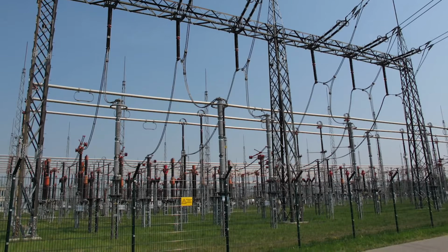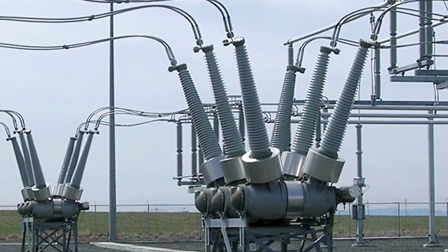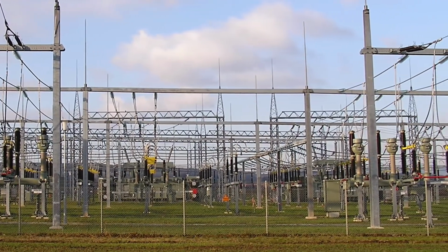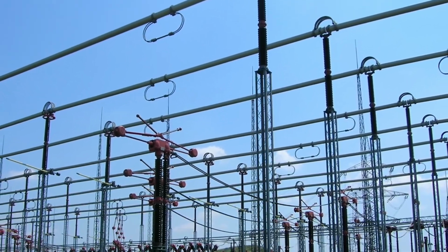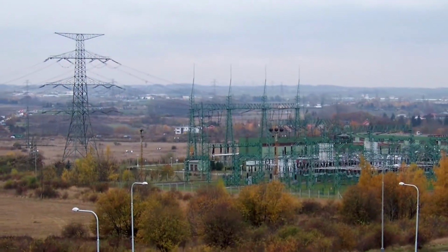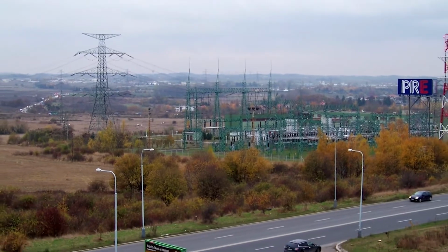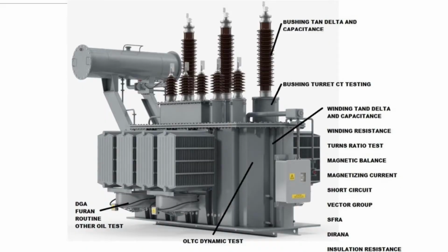Cover the transformer testing. A few of the main tests are winding resistance test, ratio test, vector group test, polarity test, open circuit test, short circuit test, insulation resistance test, dielectric or insulation test, impulse test, temperature rise test, testing on tap changer on load and off load, vacuum testing on tank, radiation, magnetic balance test, magnetizing current test, SFRA test, DGA test, tan delta test, boosting test. So these are the tests that we need to conduct on a transformer. We'll see them one by one in the next video.